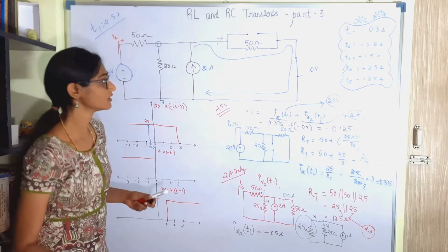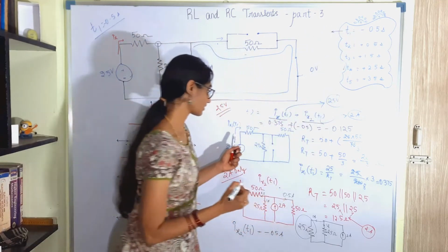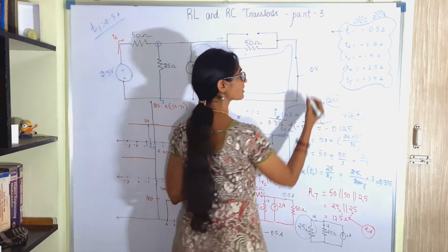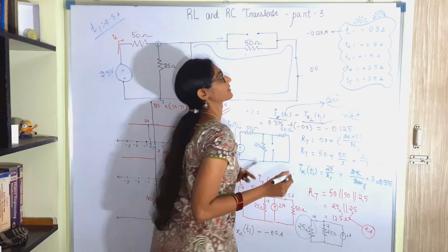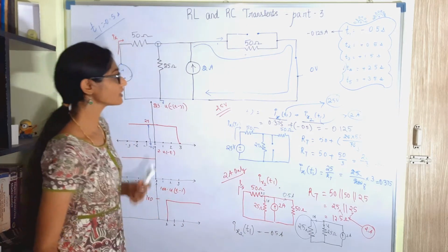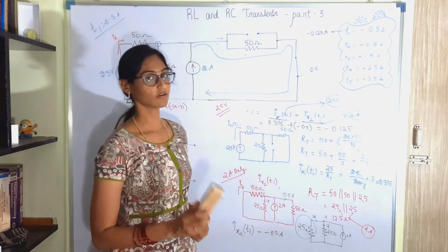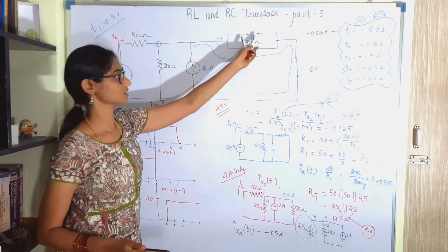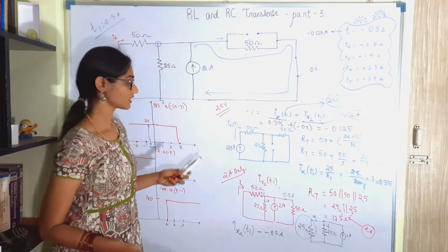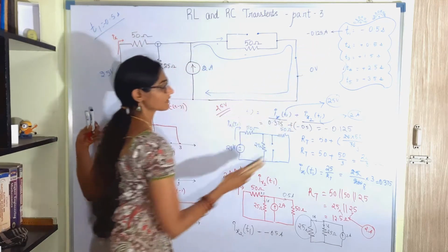Okay. So at T1, the value of Ix is minus 0.125 ampere. Okay. So similarly, for the time T2 of plus 0.5, we will find out the voltage levels at each different points, and then what is the status of the switch also we will find. Then we will draw an equivalent circuit at time t equal to 0.5 and then solve it.